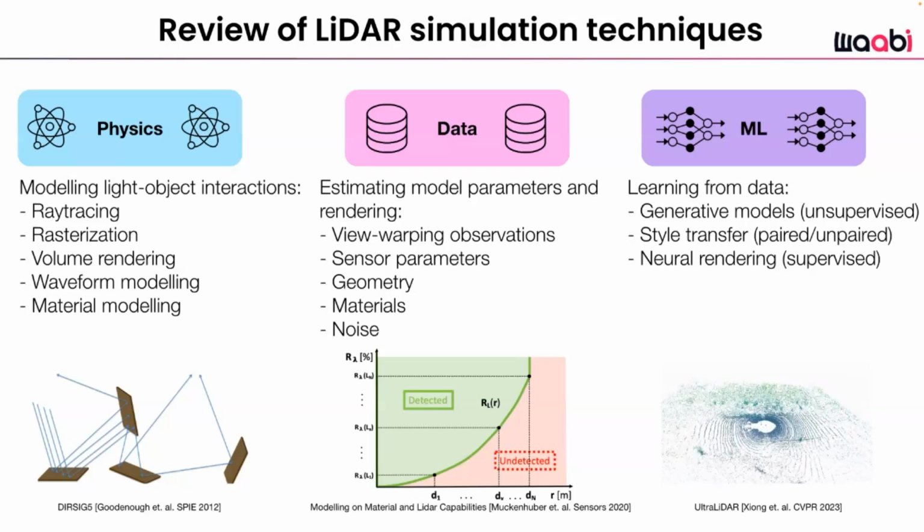On the data side of things, you have a lot of data you can collect from the real world that might be useful for modeling sensor data. For example, you can record how the LiDAR interacts with different types of materials and see at which point a particular object does not return LiDAR points, for say, concrete versus a highly reflective object.